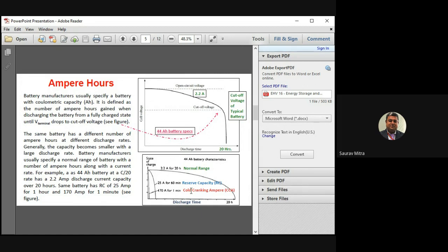Same thing happens in case of Arab countries. Their outside temperature is very high. That's why the electrolytes are always in a very highly active situation, and the battery is always in too much of an active state. So there, very easily the vehicle will start, but there is a big chance that the battery will explode in the Arab countries, which is very hot, or in Africa. So there also there should be enough cooling arrangement around the battery.